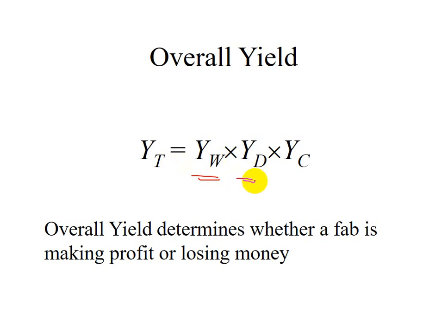For the die yield, is related to the factors such as particle contamination, process maintenance, and total process step. The more process, the lower the die yield. The packaging yield related to the wire bonding, quality and specification difference between the die test and the chip final test.